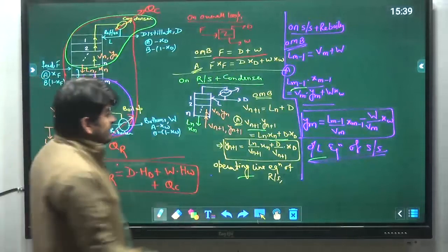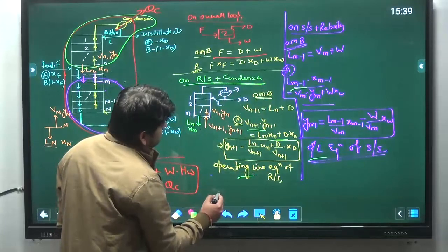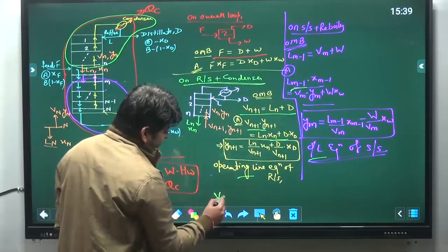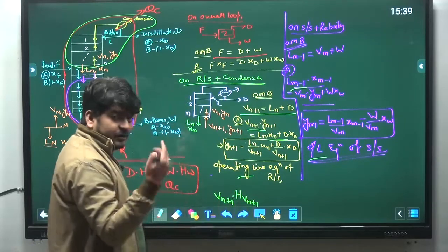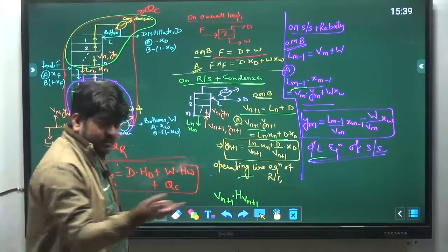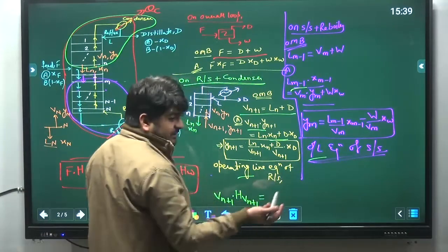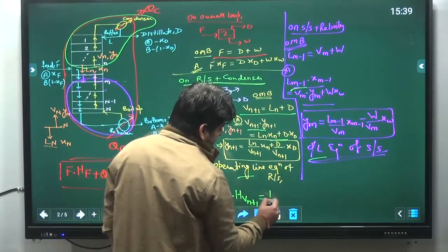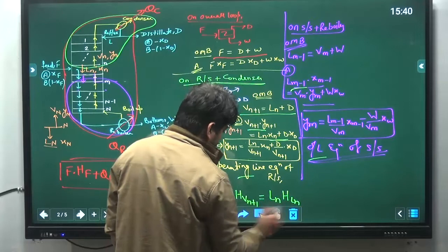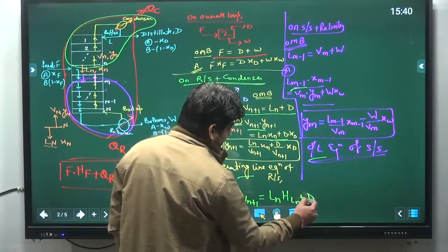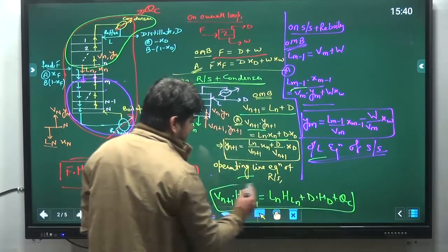Yes. Similarly, for this part, rectifying section plus condenser, the energy balance will be: Vn+1 multiplied by Hv n+1, the molar enthalpy of vapor on the n+1 stage, equal to total enthalpy out, that is Ln into HLn plus D into HD plus QC. This is the energy balance for